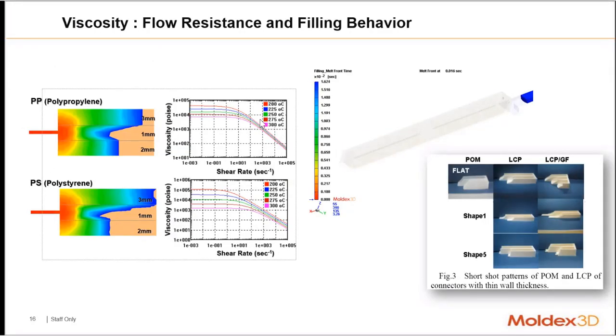And as you know, viscosity is very critical to the flow resistance of the melt in the cavities, and it also has a strong influence on the feeding behavior. I think for most Moldex3D applications, maybe not more than 80% are to solve feeding problems. So it's highly related to the viscosity measurement.